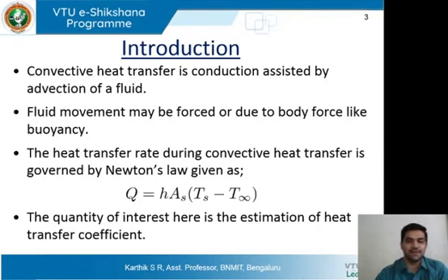of a fluid. So here you will invariably have a solid surface upon which there is a fluid which will be moving. Now you have to recognize that the movement of the fluid is a bulk movement, which means there is a macroscopic movement of molecules due to the temperature gradient which is prevailing.